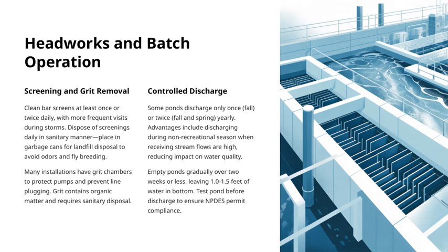When emptying ponds, do it gradually, over 2 weeks or less, and leave about 1 to 1.5 feet of water at the bottom. Before discharging, always test the pond to confirm compliance with NPDES permit requirements. This careful approach helps protect water resources and ensures regulatory compliance.